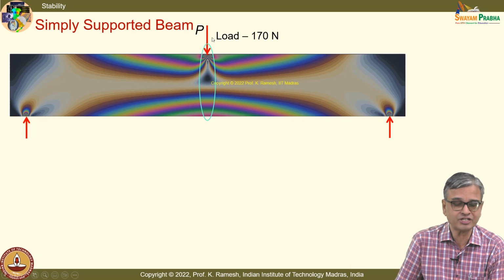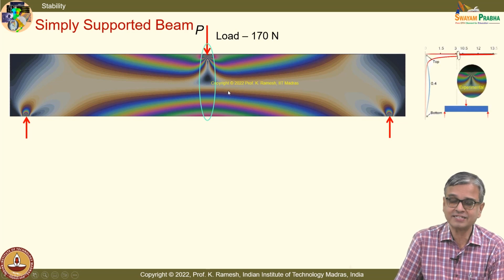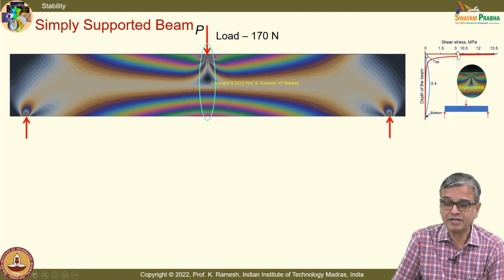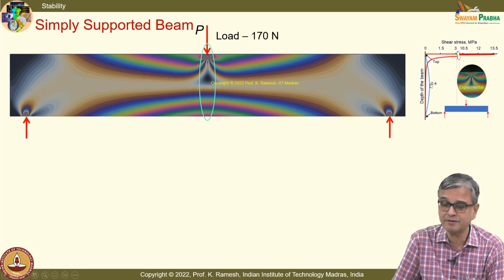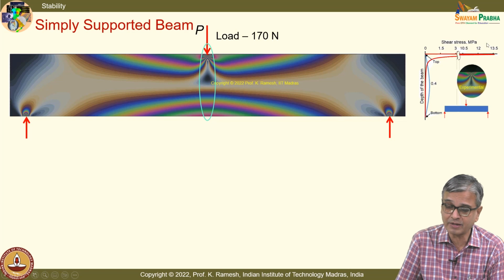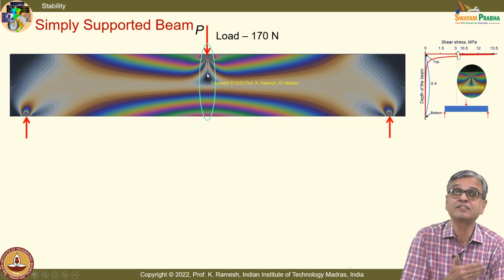When you are looking at shear stress, there are many places where you can ignore it, but you cannot ignore it near the load application point. Near the load application point, your strength of material result of parabolic variation is absurd. The shear variation is very, very high just below the boundary, but on the top surface it is still 0, because it has to satisfy that free surface requirement. And these stresses are comparable to your bending stress. So, failure can happen unless you strengthen this.